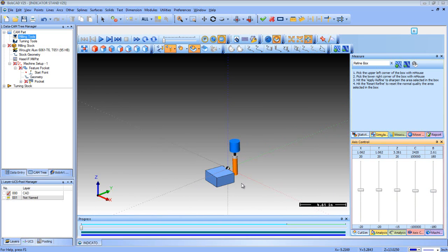And again, you can come back and add your geometry at any time once you have it all created, or acquire it. So again, nutating head, table, machine. Nutating meaning that the axis of rotation is not aligned to any of the existing axes of the X, Y, and Z. So you use the sine of the angle to configure that. This concludes this lesson.